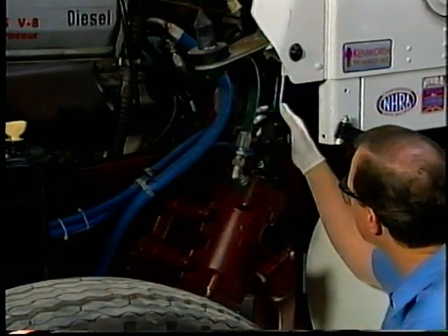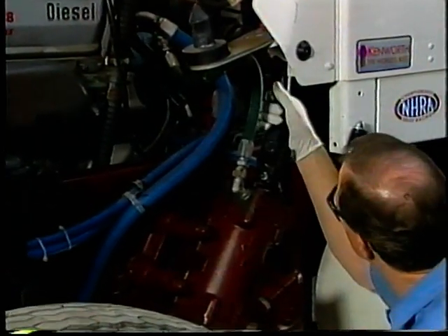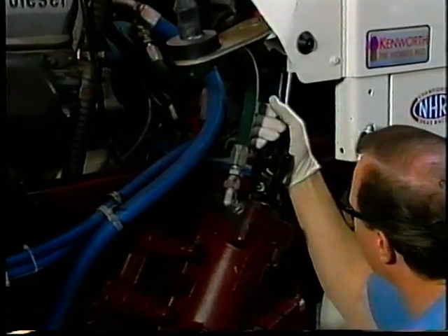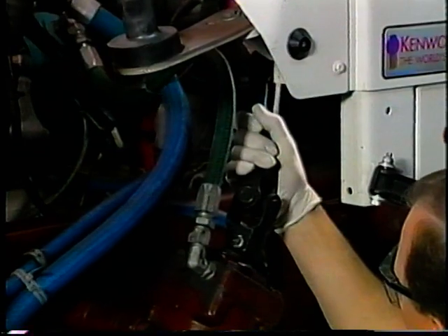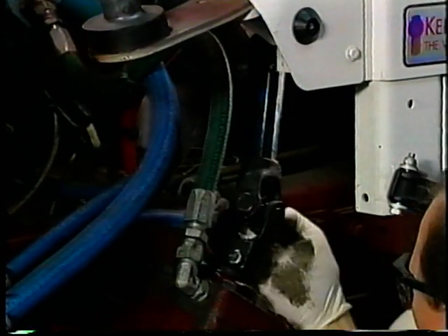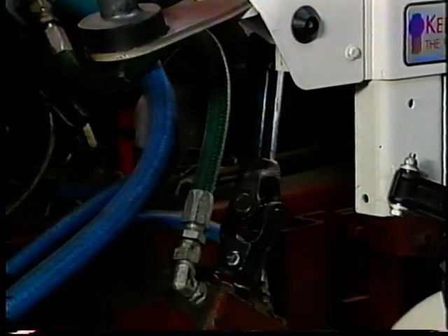If the front steering bushing is okay, check the column to cab mounts and the U-joints in the steering column. Push against the joints with your hands to test for looseness, and never use force that could damage the tension spring in the joint.